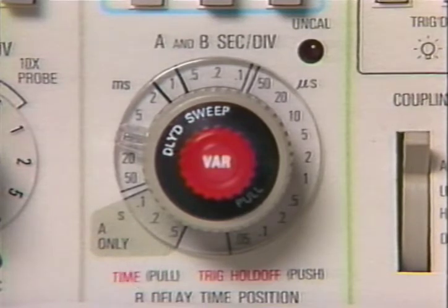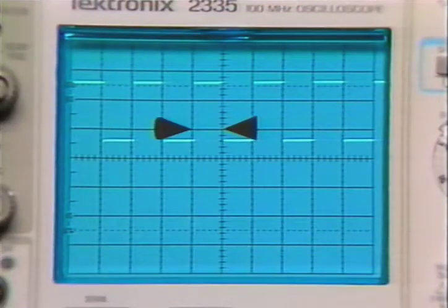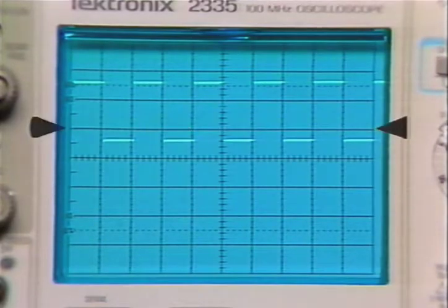Like the vertical system volts per division switch, the time base control's markings refer to the screen scale factors. If the seconds per division setting is 1 millisecond, that means that each horizontal major division represents 1 millisecond, and the total 10 division screen width displays 10 milliseconds.